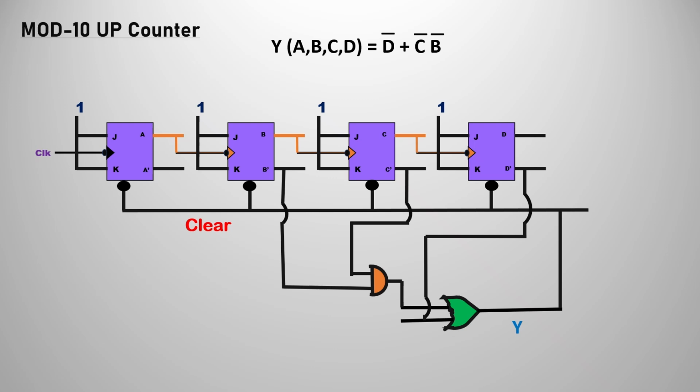With the help of the truth table only we are going to decide this. So suppose you want to implement mod 6, just put all the ones up to the 6th position and leave all the remaining as 0. That is the simple thing. By filling the K-map, you can get the output expression Y. In the same way you can do mod 6 also.